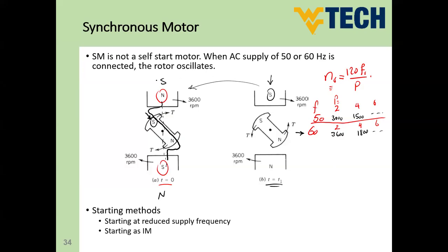because the electrical speed is high and the mechanical speed is low in the transient period during turn on, we need to reduce the supply frequency, or in other words, we need to have a small relative speed between rotor and stator poles. So in the beginning of the motion, the motor is at standstill, which means it has zero speed.